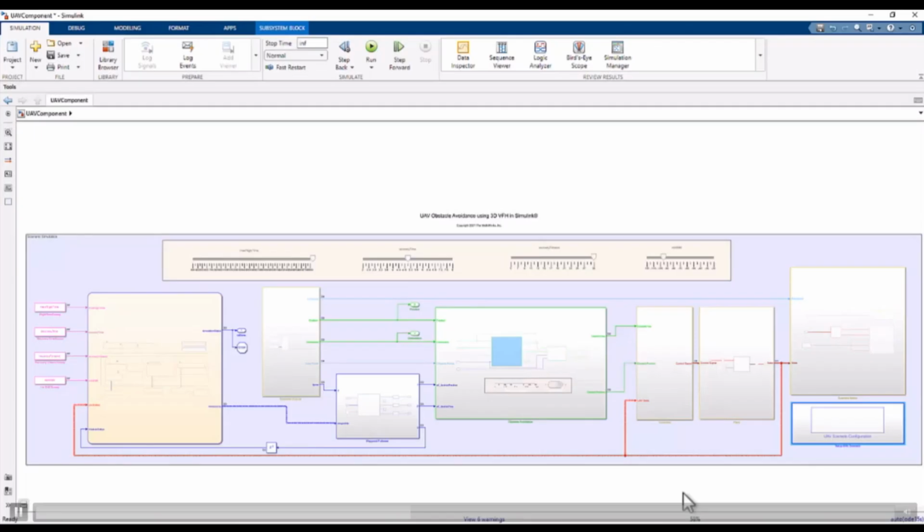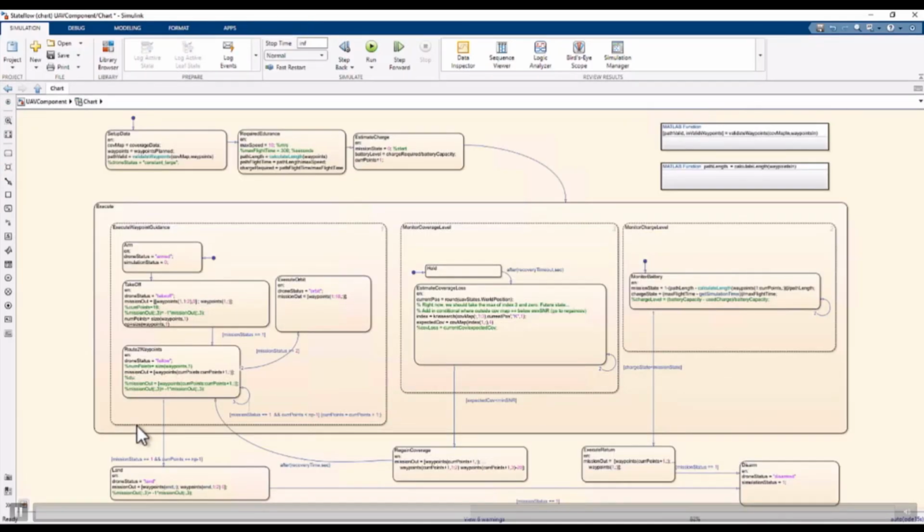Regarding the controller and plant, the controller converts the desired position and heading to control commands for the drone. All those commands are then sent to the plant model, which represents the quadrotor dynamics. This is a block inside of my model. I don't know if you know, but this quadrotor block we are using captures the essential flight dynamics needed for mission-level analysis.